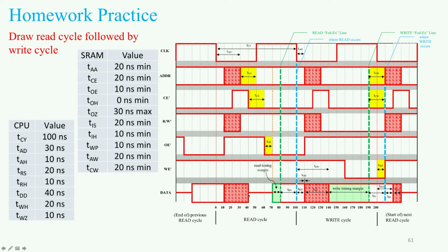And then there's some transition while the SRAM attempts to get its signals off of the bus and put it into a floating state, so that somebody else can potentially drive the bus. The time that takes is 30 nanoseconds, and this begins at the end of the hold time. It'll do its hold time first, which was 0, and then it will begin transitioning to high impedance, which is 30 nanoseconds. We see that 30 nanoseconds takes place here. So output enable flipped to high, then 30 nanoseconds later, the data bus was transitioned into the correct high impedance state. And in this space in between, the signal is unknown.